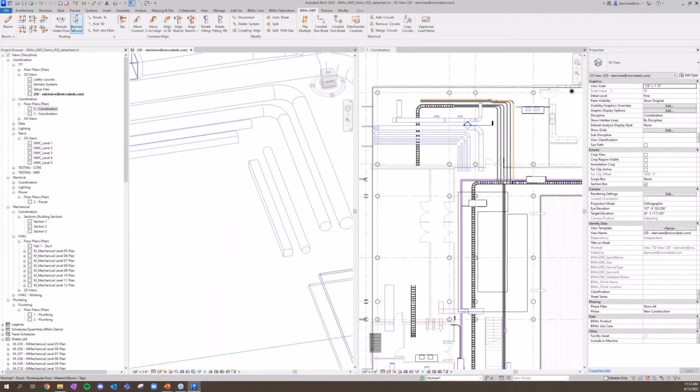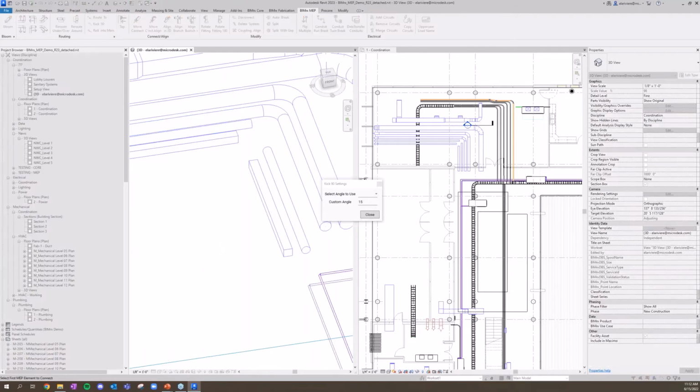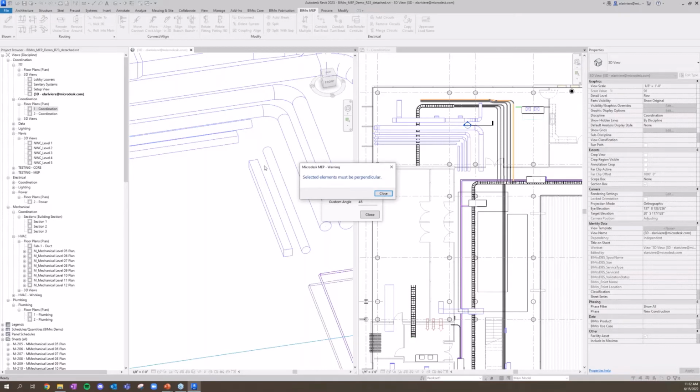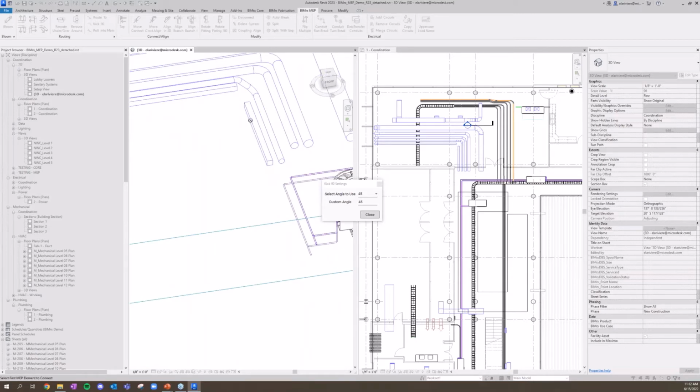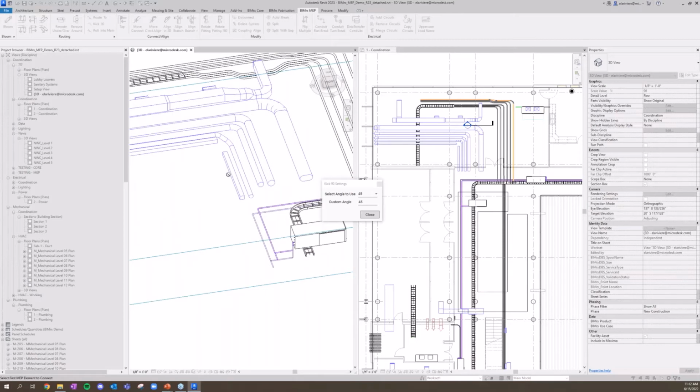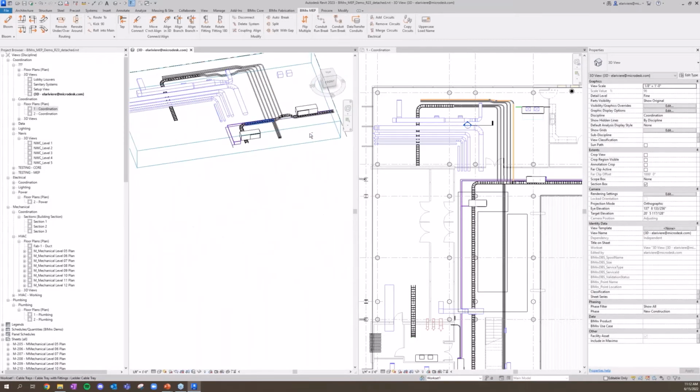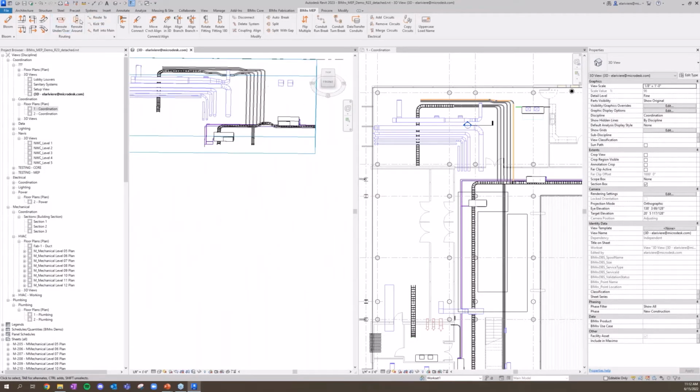If I zoom in on that piece of duct and we use kick 90, it's asking me to choose a side that I want a 90-degree bend and choose a side I want another bend. Because it's ductwork, I think 45 degrees makes sense. So if I want to 90 up and come flat, I can 90 up and go flat. And we see that 90 to a bend. You'll notice it's not working on square duct. I do think it's pretty fair. We can't arbitrarily rotate a 90-degree square bend. So those are a couple of those auto route commands we have up there.